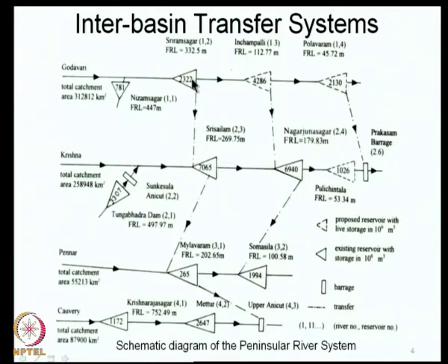Then we will see what is happening to the downstream reservoir of the same basin. If a downstream reservoir of the same basin is in deficit, and this reservoir is in excess, we will meet the demands of that basin through this. Remember, when I say you meet this demand from this reservoir, it is not for individual time periods. Not every 10 daily time period do you supply from here and so on. You have to simulate this system and run the simulation model a large number of times and then arrive at certain policies. Now, in arriving at such policies, you need to define the priorities.